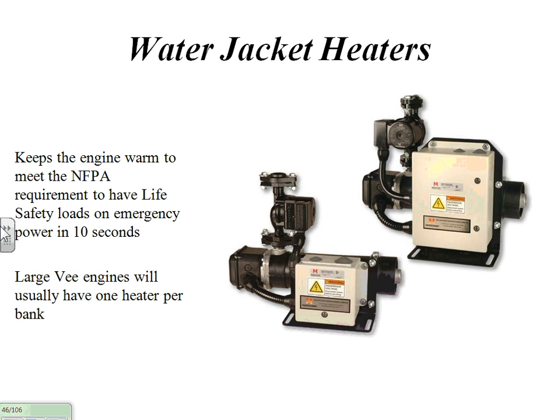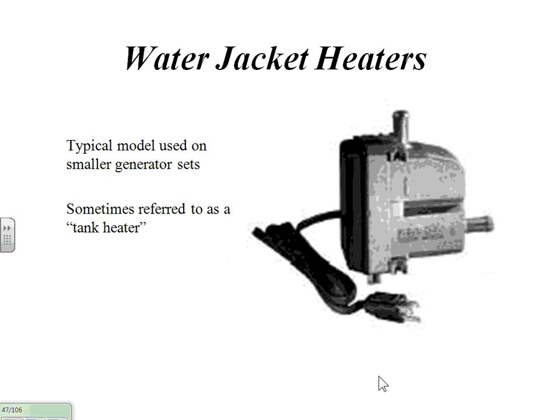Okay, and water jacket heaters on a big V block like I showed you in the pictures, the one in the truck and in the trade show, you're going to have a jacket heater like this on each side, each bank of the cylinders. Smaller ones will get a little tank heater like this. You can probably see and buy one of these for your car. Little Kim hot start heater.